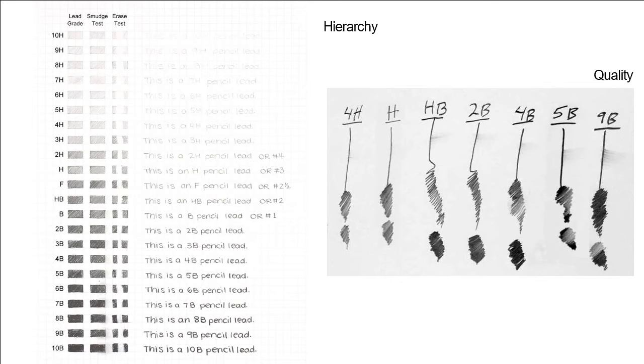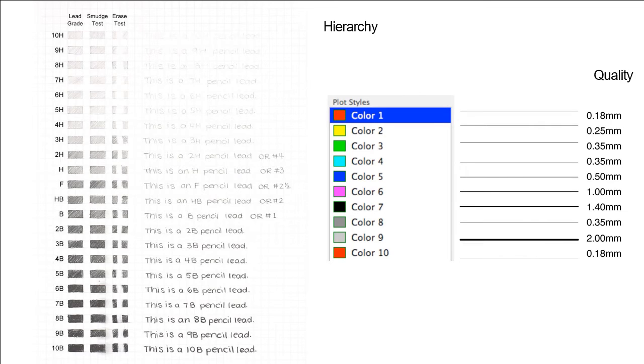One of the skills that you're going to develop as a designer is the ability to make lines that have different darknesses and different widths. We refer to this collectively as line weight. For this class, of course, you'll be creating those line weights in AutoCAD. There are standards, again, that you will need to learn to follow. Every office has different standards, but a drawing absolutely must have a clear hierarchy of different line weights.